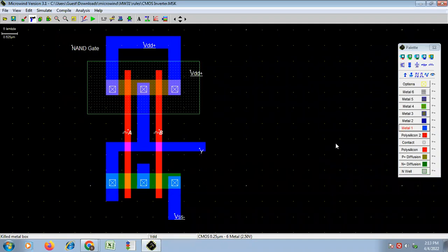So we will have to add an inverter. Simple. AND is the opposite of NAND. So if I add the inverter and give the output of NAND gate to the inverter, and take the output from the inverter, it will act as an AND gate. Okay, let us do it.